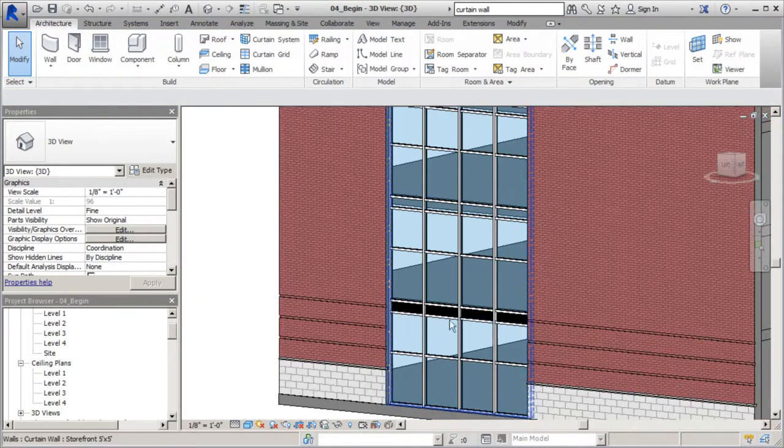This will help you out, especially if you're working with some high-rise buildings where you might need to hide what's going on at each level. Now, you're not just limited to using the black color. You can use any of those colors that were on that swatch. But if you wanted to control the amount of visibility through that particular panel, mess with your transparency like we did. So I'm excited to be able to show you this one. So this is some of the in and outs of working with your curtain panel system.